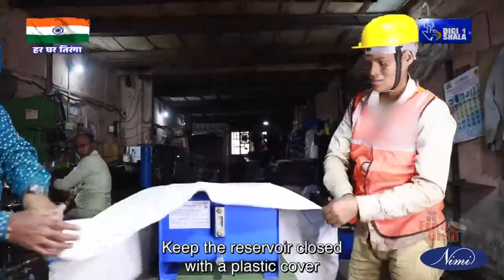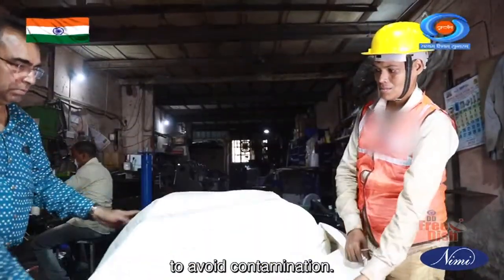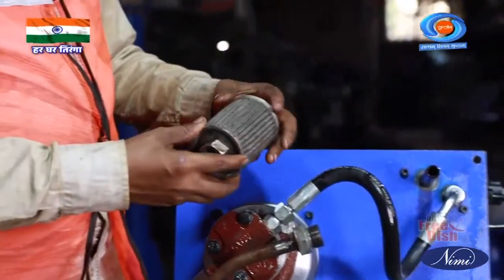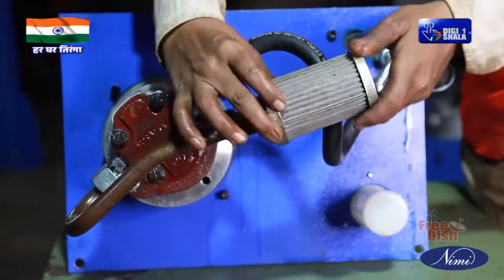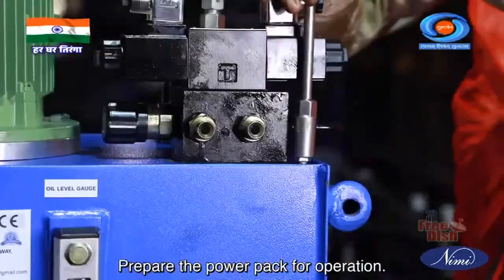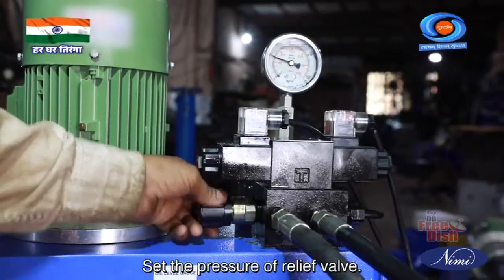Keep the reservoir closed with a plastic cover to avoid contamination. Remove the strainer to clean and assemble it. Prepare the power pack for operation. Set the pressure of the relief valve.